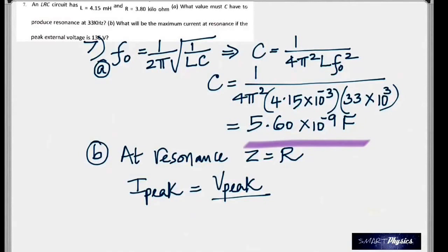Now can you tell me, is the impedance maximum or minimum at resonance? Impedance is minimum because, just mathematically look at that, this whole term became 0. And impedance is equal to resistance. So impedance became minimum, which means the current becomes maximum. That's the idea. So therefore the current at resonance is maximum because this is a minimum value now.